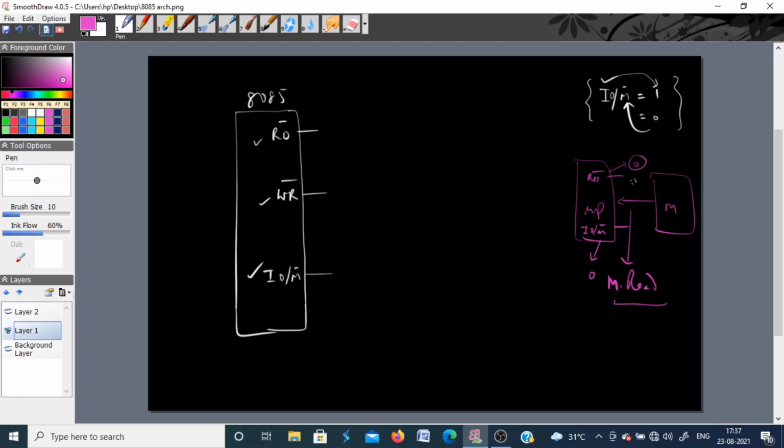Okay, so by combining this 0 and 0, you can generate a separate control signal which is specifically used for memory read only. Okay, because on the memory itself we have 2 pins now, one is for memory read, one is for memory write. Okay, it means what the processor has to do, if it has to read some data from the memory, this read signal must be activated.